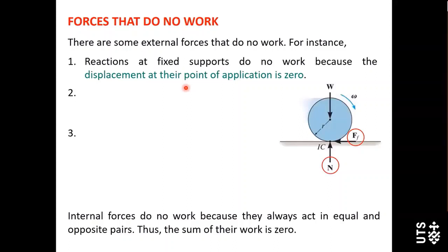Reaction force at fixed supports cannot do work. Why? Because the fixed support doesn't have any displacement. That means the displacement at the reactions' point of application is 0.